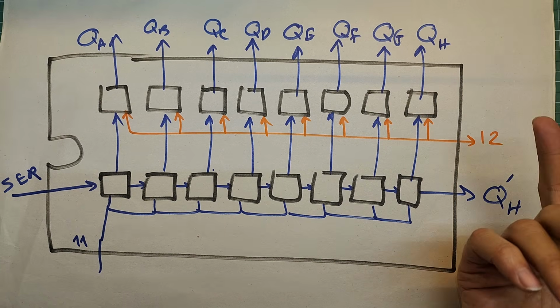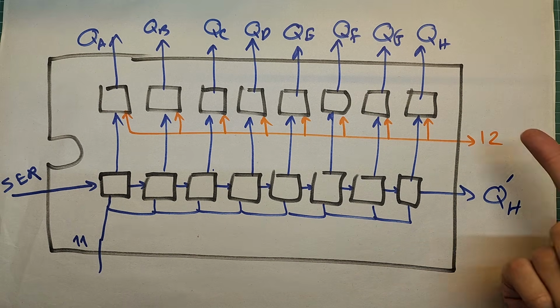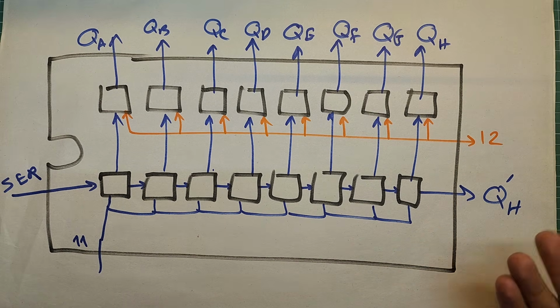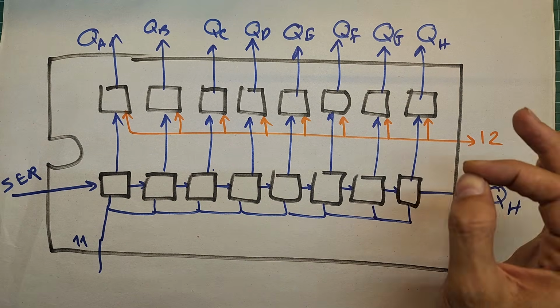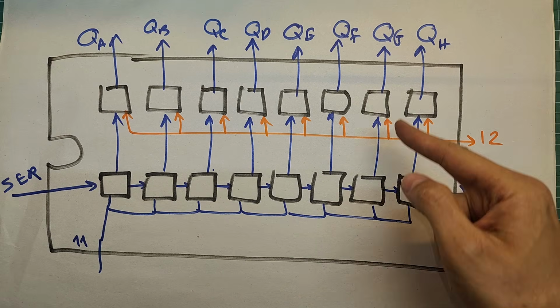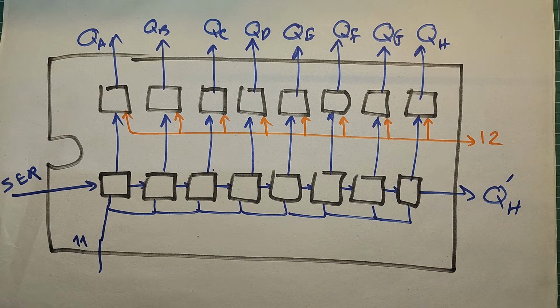The reason for having this copy of QH here as an output is also the same. If this pin didn't exist, the shift operation wouldn't happen because the value of the main QH pin here only changes when pin 12 is clocked, and it practically can't shift data to the next IC. Besides all of these, I also want to point out a few other electrical tips regarding these circuits that are good to know.